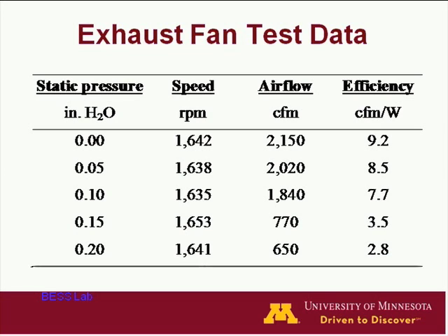Way over on the right side, there is an efficiency rating as well, CFM per watt. That is, again, an assessment of how energy efficient the fan is, how much airflow is produced by the fan at that static pressure, against how much energy is inputted into the motor.